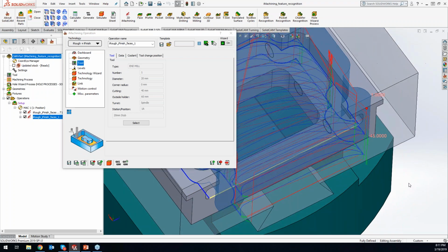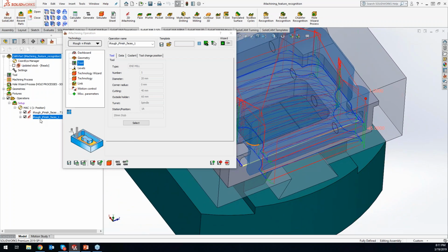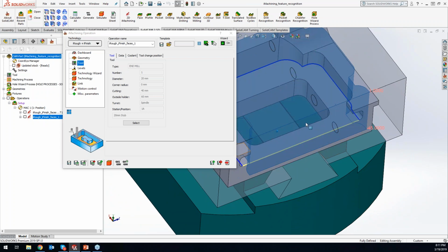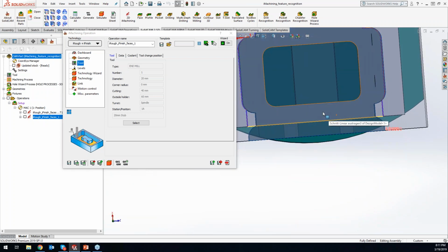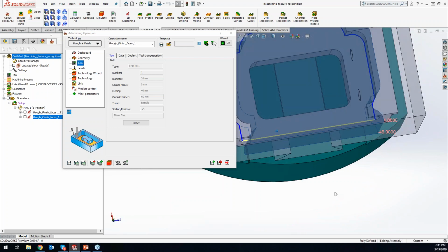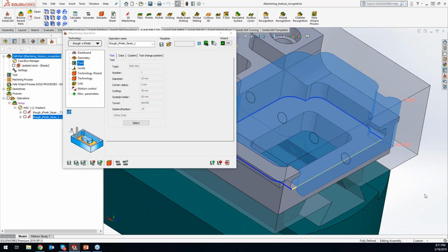And we can see the solid blue line of the selected geometry in contrast to the tab of the 3D model, which the iMachining is staying away from. Yep. So we're actually using the model itself to protect the tool path from gouging into those tabs.